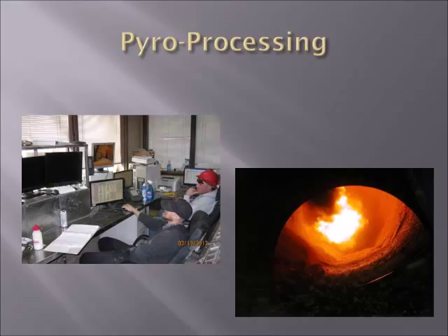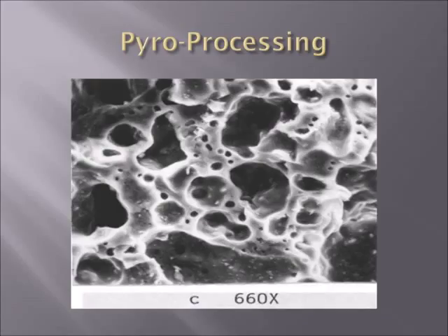In the burn zone, the temperature is maintained at approximately 2000 degrees Fahrenheit. Once the material drops out of that burn zone and into the cooler, it is now a vitrified ceramic aggregate. The encapsulated gas voids attribute to the aggregate's density, absorption, thermal, and acoustic properties. The hard ceramic matrix is what gives it its strength. Together, these two properties are responsible for ESCS materials' consistent and exceptional performance in concrete.